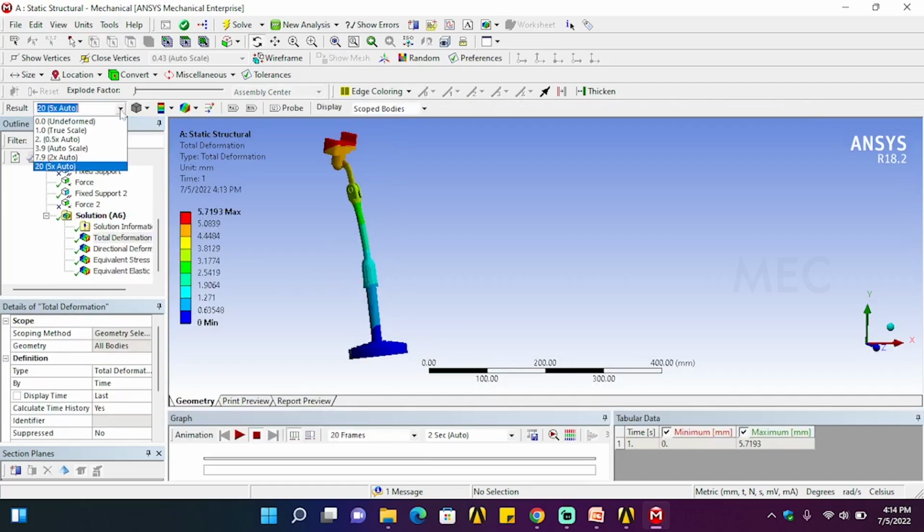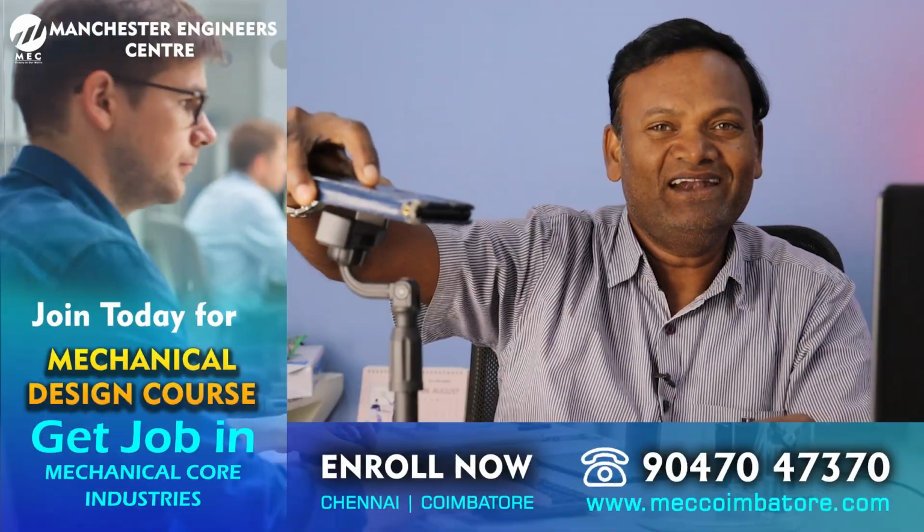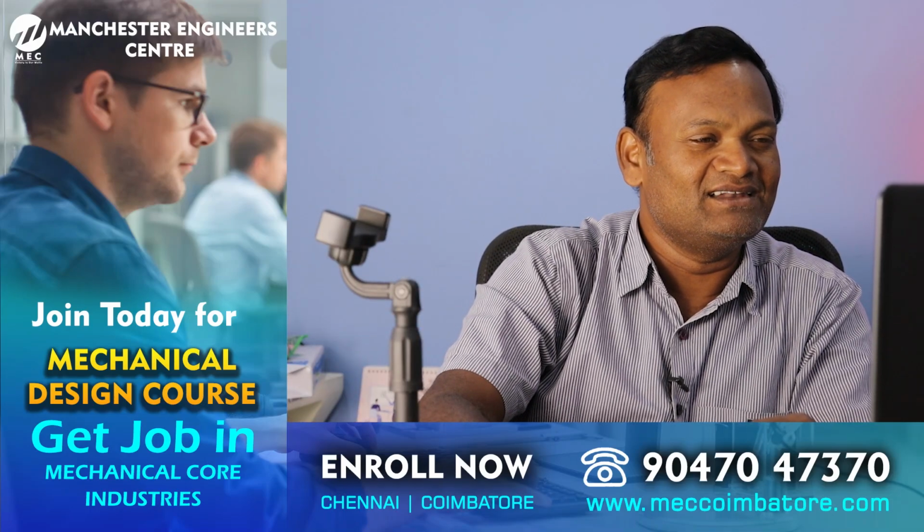Before the deformed shape, I can see the undeformed shape. This is my undeformed shape. The total deformation is around 5.7 mm. This is only one mobile load. With one mobile load I am getting around 5.7 total deformation, and stress is around 4.6 megapascal.